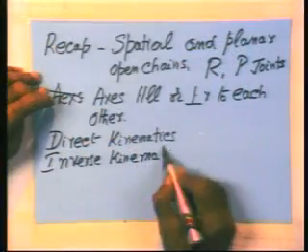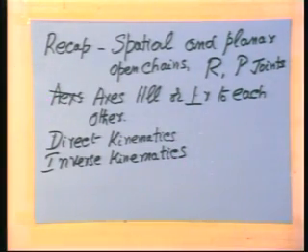In addition, we had seen what is known as resolution, accuracy, and repeatability. The most important of these is the repeatability, because whatever your robot does, if it repeats continuously without error, you are very happy. Accuracy, yes, more expensive robot used in very small workspaces, you do need accuracy. Then the resolution, what is the minimum distance the end effector can go, because that depends on the resolution of the various elements. Also, links are subjected to forces, consequently they bend, there is backlash, all these decide parameters like resolution, accuracy, and repeatability. We had seen that also.